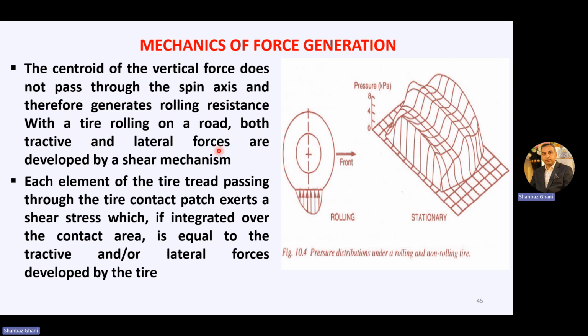Both tractive and lateral forces are developed by a shear mechanism. Each element of the tire tread passing through the tire contact patch exerts a shear stress, which integrated over the contact area is equal to the tractive and/or lateral forces developed by the tire. So we have to integrate it over the whole contact area.